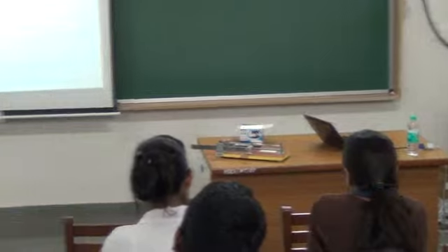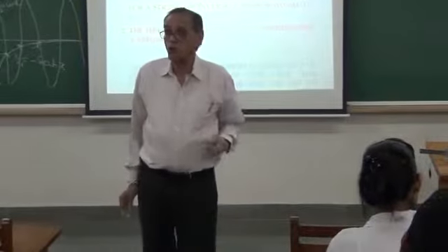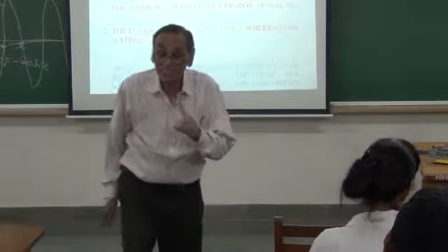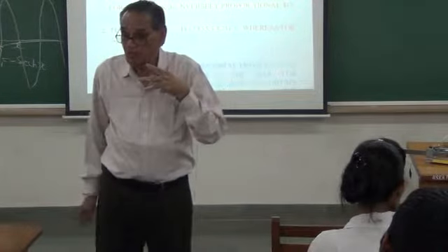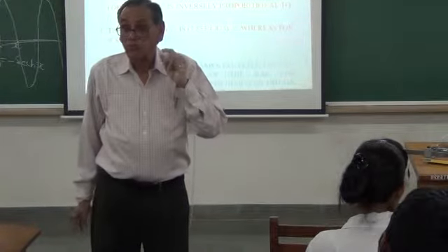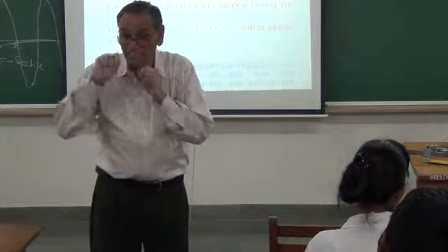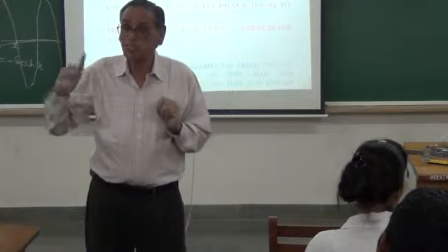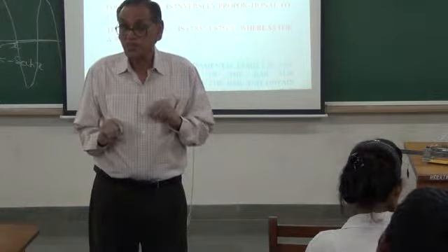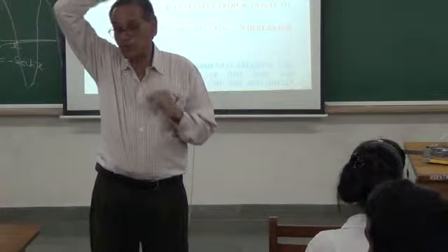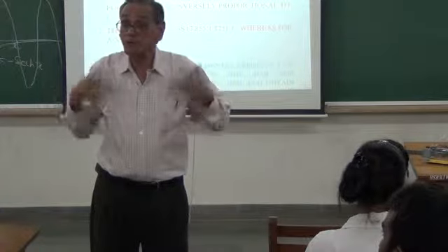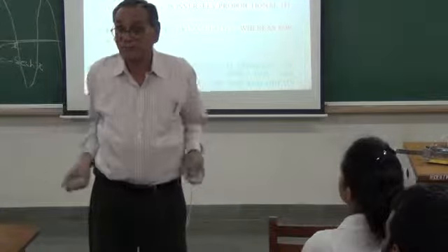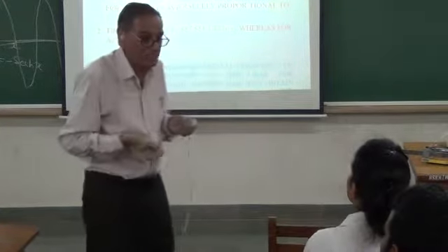After noting the fundamental, I must note the overtone. The overtone is 6.22 times the fundamental. The force required to produce a displacement at a frequency omega is proportional to omega square. So at 6.22 times the frequency, I have to apply 36 times the force to produce the same displacement.